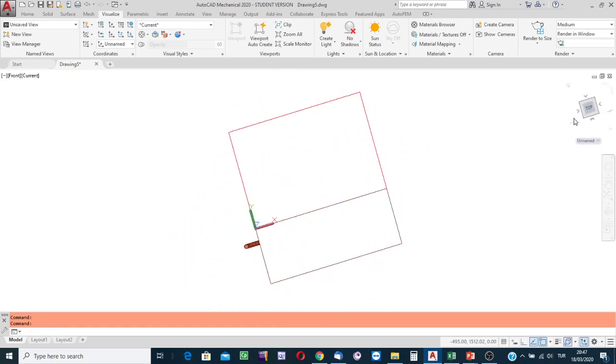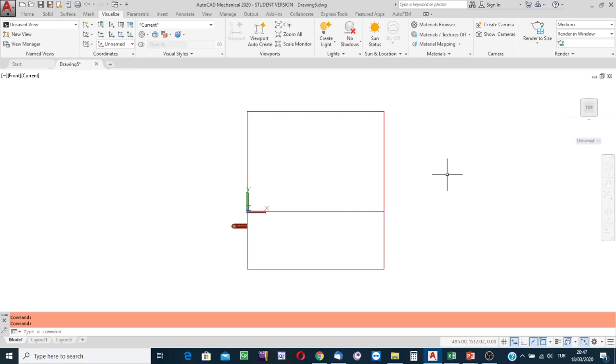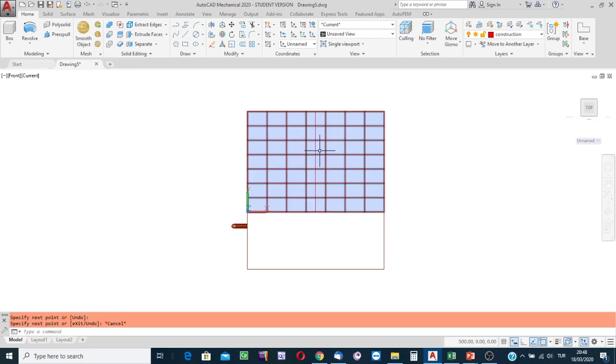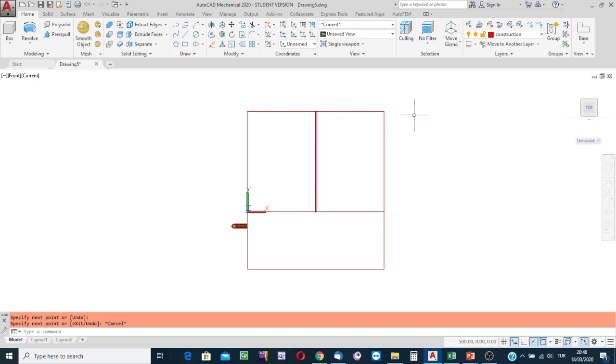And then in this example, the axis of revolving will be the one extending from the midpoint of the boundary of this work plane to its opposite side midpoint. So start the line drawing process, piece of straight line, and then indicate this point as the terminal point of the line and indicate that midpoint as the other point. I'm going to use this line as the axis of revolving.